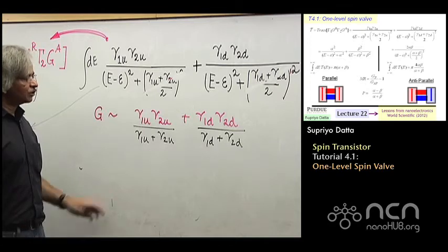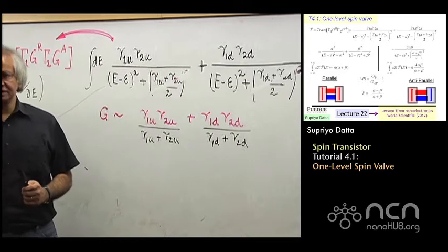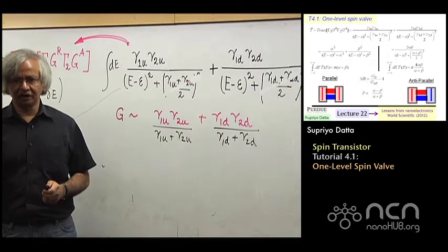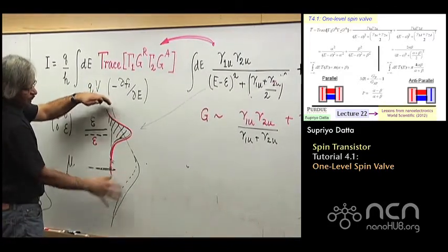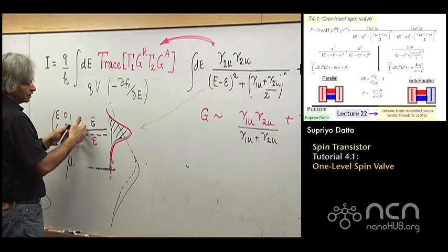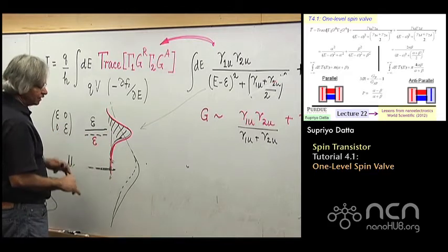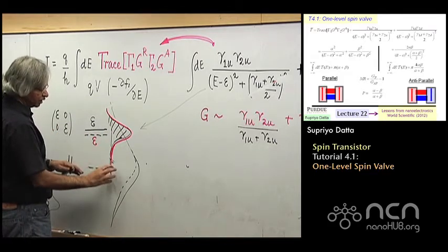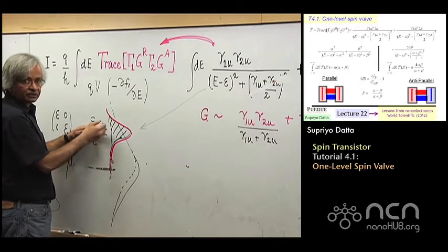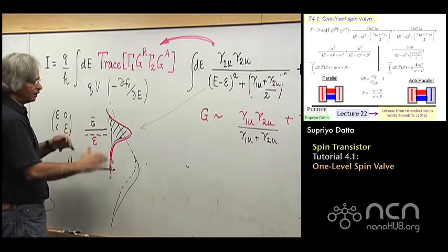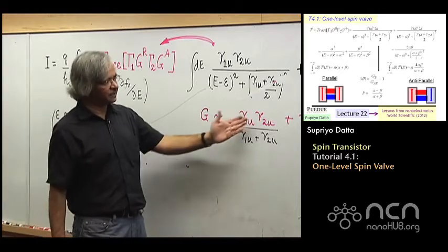And so this is the form that is more appropriate for the GMR style devices, the ones where the channel is actually a conductor, where conduction takes place over this entire range, and electrons are actually going through these levels at these energies. Whereas with tunneling conduction, the important conduction is by electrons down here, and their energies don't even match your levels. They're way out, and they're just tunneling through. Now we are talking of electrons whose energies actually match the level and go right through it. And then you'd have something like this.